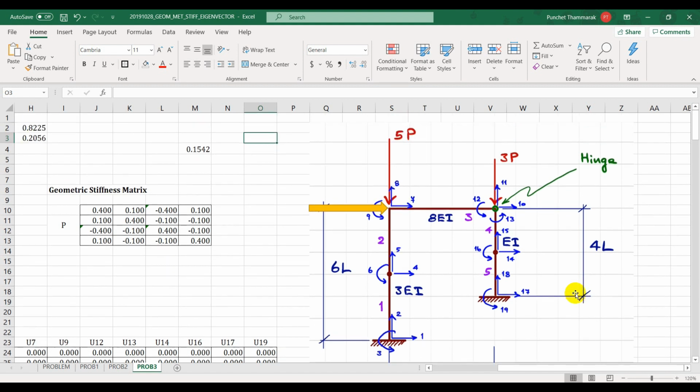We will plot the deformation versus the axial load like before. The x-axis will be the deformation, like I used to plot for you in the bifurcation problem response. And the deformation that is sensitive, we will plot in one problem. You have so many deformations, right? You have rotation here, displacement here, vertical displacement here, and so on and so forth. But what would you pick?